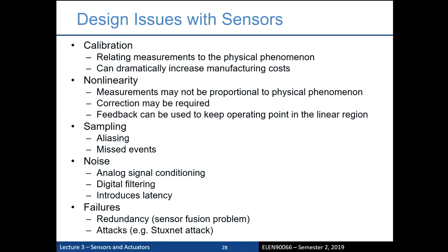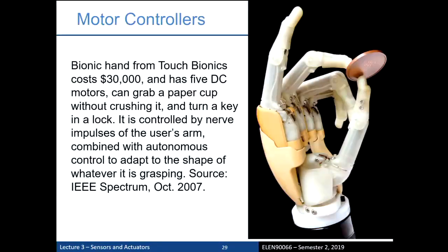All right, so sensors are messy, but we have to deal with them, and as I said, there are all the issues that we have with them. On the actuator side of things, most actuators are, as I said before, motors really. Whenever I think of an actuator, I think of something spinning, something moving on a gear base or something like that. To give you an idea about the difficulty of dealing with motors: motors are terrible to deal with. They are slow, bulky, inductive, they heat up, they spike things with massive voltage spikes, and they need a lot of